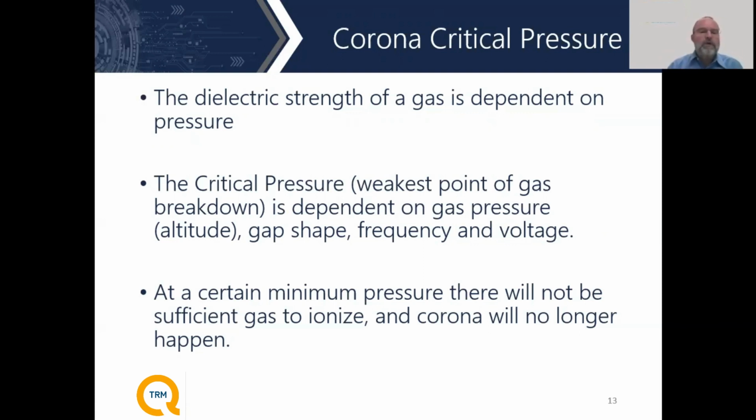And at a certain pressure, you will not have enough gas to ionize, and therefore the voltage standoff will start to become higher again. That's where they define the critical pressure. At sea level, the gas has a certain amount of pressure.